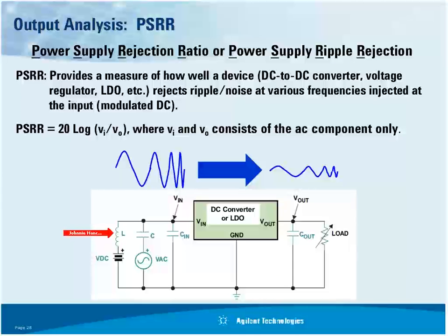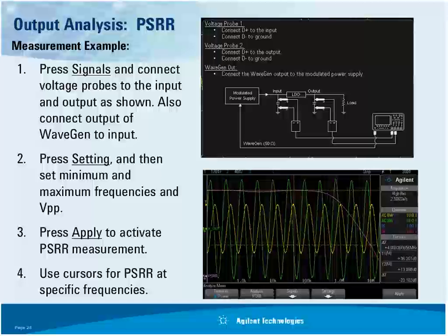and capacitance. If you just connect the generator directly without coupling it in, capacitive coupling, if you just connect this generator directly to this point without these inductive and capacitive elements, the DC input looks like a low impedance. It's going to short out your function generator, and the function generator looks like a low impedance to the DC input. So you've got to create a summing network or purchase some network analyzer components that do this for you.